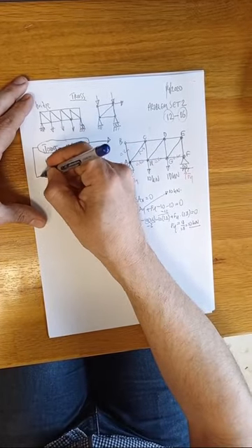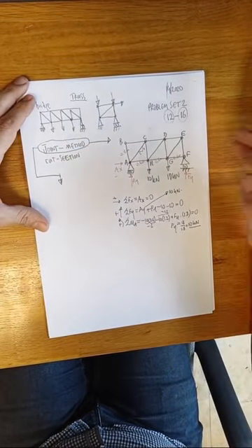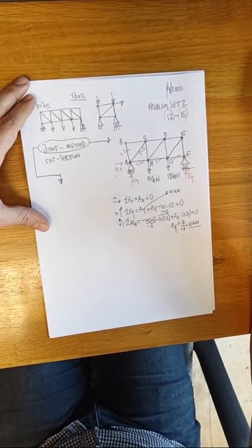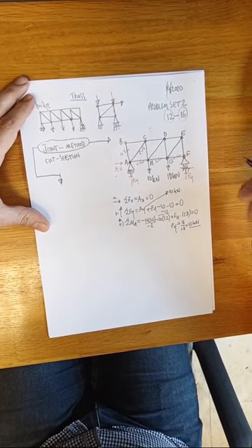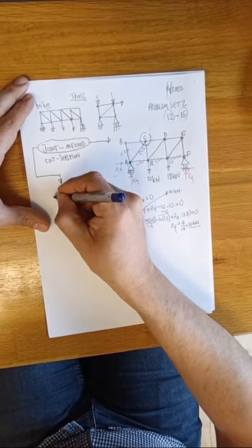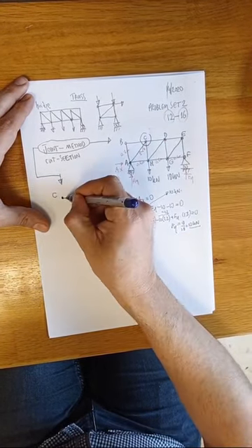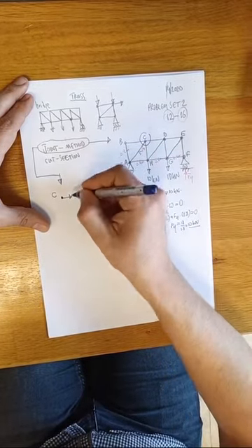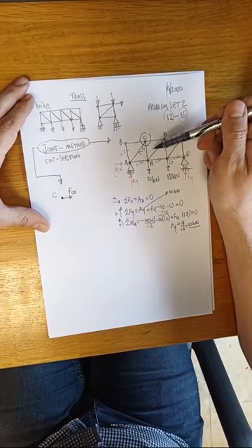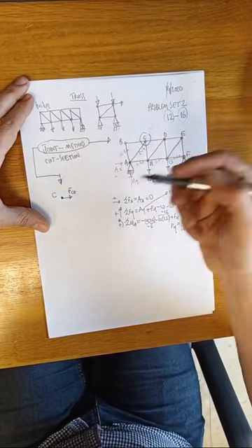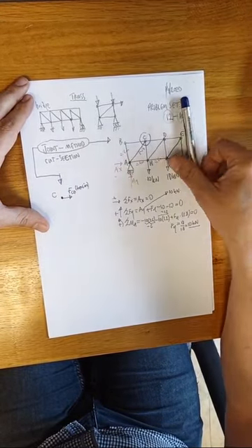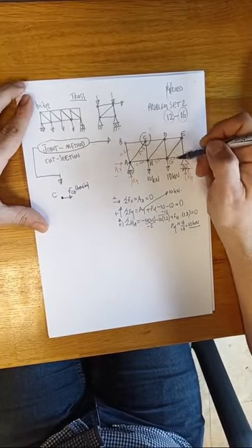Now, what is the joint method? In the joint method, you have to choose one of the joints individually and analyze it. If you start to analyze from joint C, what will you see at point C? C has these forces on it. One of them is this, FCD. I'm taking all internal forces, the forces inside the members, as tension forces. It is pulling point C. It means CD is in tension.